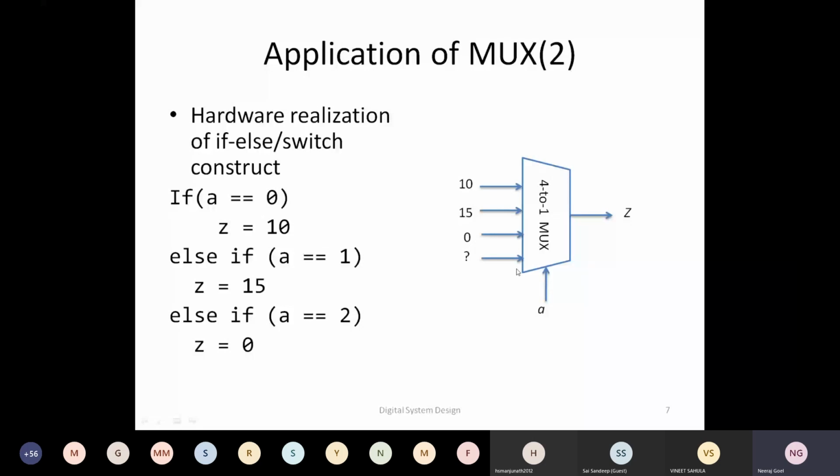Sometimes our synthesis tools are also very smart. If they see that there is no input connected, they will try to burn out or purge the components which are not actually required or not actually used. So this smartness of the synthesis tool will take care of it if you are not providing any particular input or any particular output.